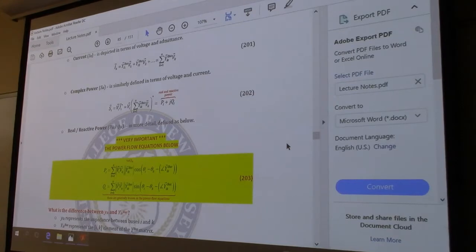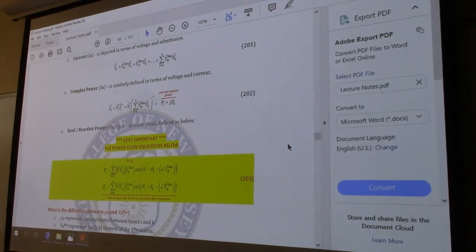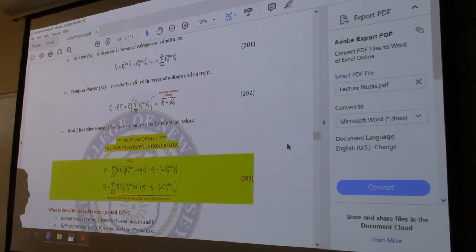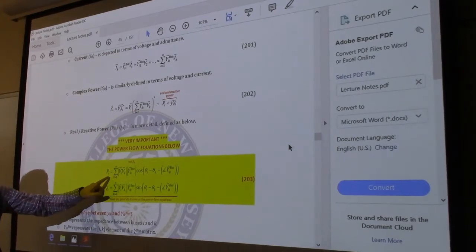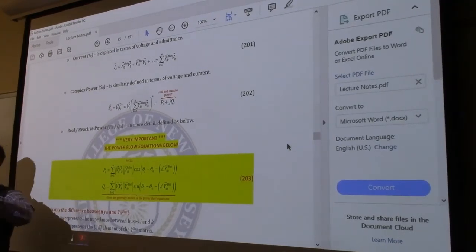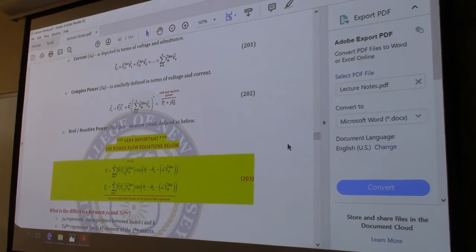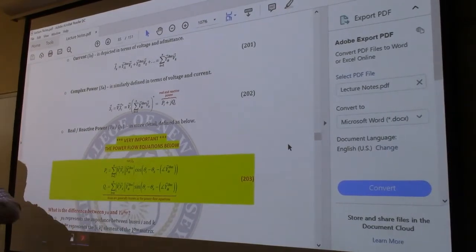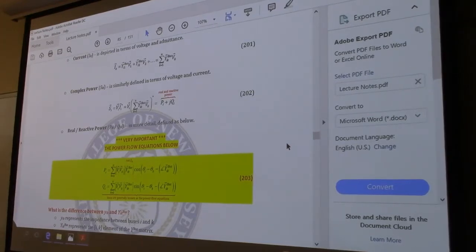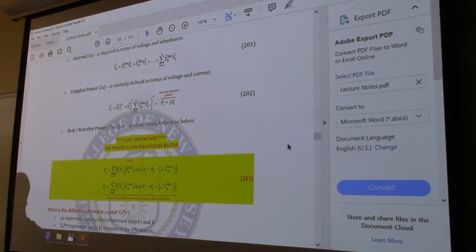They look a little bit complicated, but when you break them down, you'll see that you know all the individual pieces. First thing, sum from k to N. All this is saying is that you have to consider all the different lines going out of the bus. From k equals 1 to k equals N, where N is the number of lines going out. So let's say there's 3. You have to consider line 1, 2, 1, 3, and 1, 4. All right?